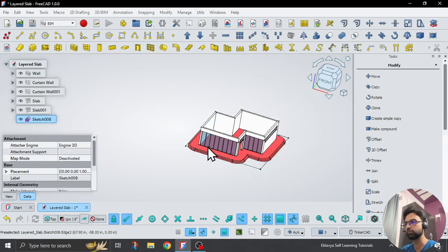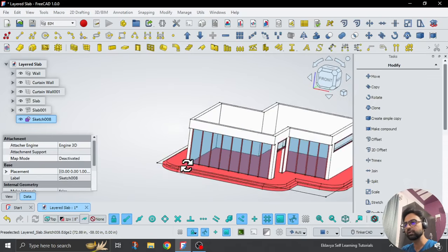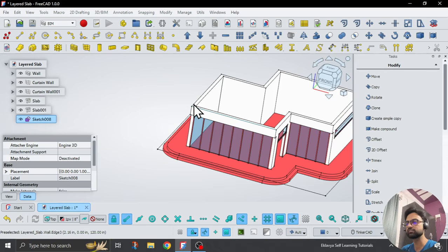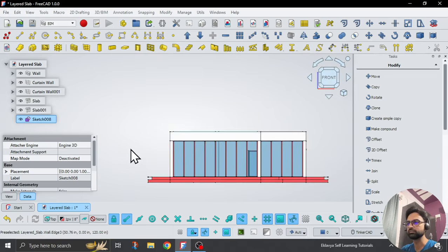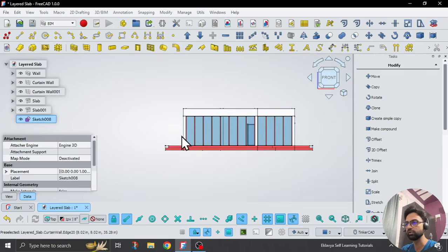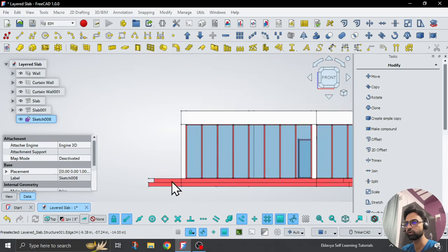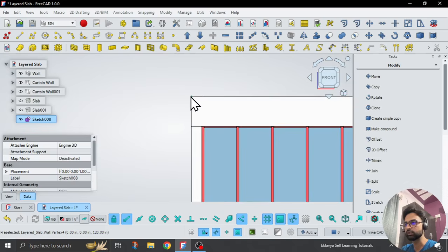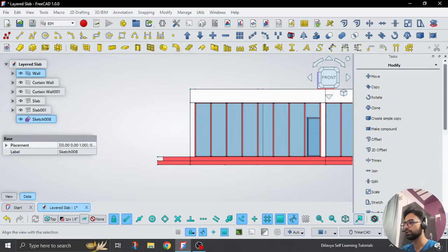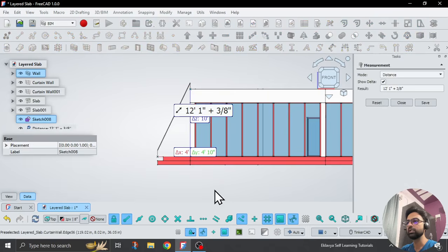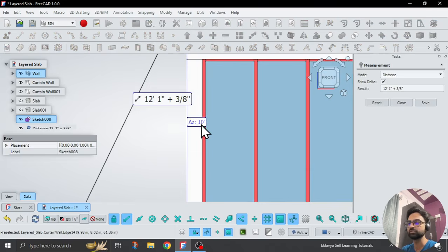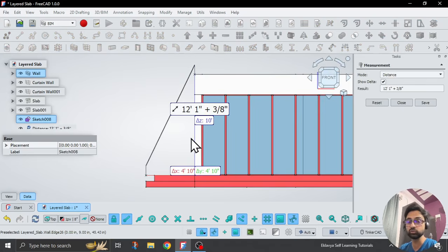This is at the bottom. You could have taken the uppermost surface as well. So this is around 10 feet, the height overall. If you want to quickly measure, just take this point and then this point holding your control key and click on the measure tool. It will give you the delta Z, which is 10 feet, right? So this measure tool is sometimes really helpful, guys.